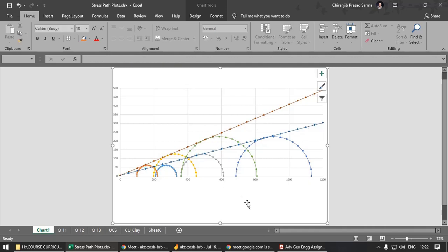Obviously, when we define shear strength parameters of a soil, we should always take the effective stress parameters. We should either observe, measure, or at least estimate the pore water pressure generation there, and then do whatever analysis we need to do. As far as possible, we should always take the effective stress parameter. In certain cases, of course, when there is a significant amount of very quick shearing, and the case is undrained, we may go for looking into that aspect.